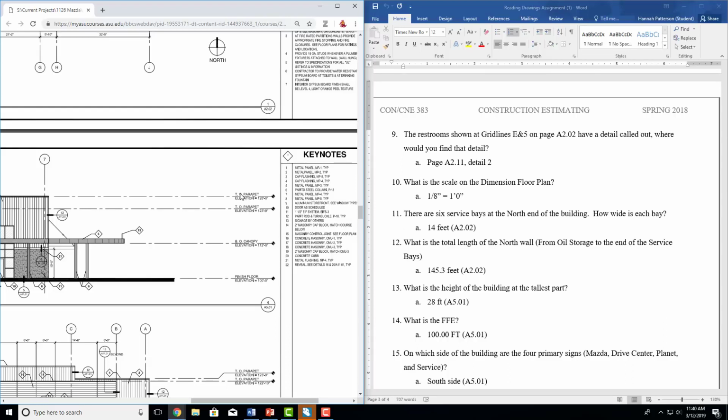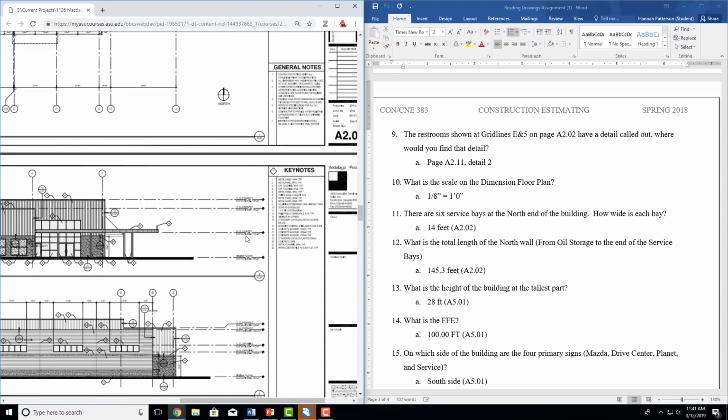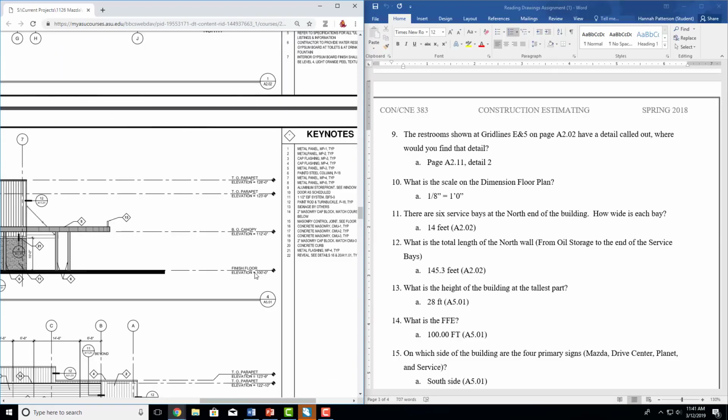In general, your standard buildings will have 10-foot floors. That's a really good, rough number to use. So a building that is 128 feet tall would be about 13 stories, and if you look at this, this is not 13 stories. So just think about it: my building is not going to be 128 feet. So your building is 28. That also answers the next one.